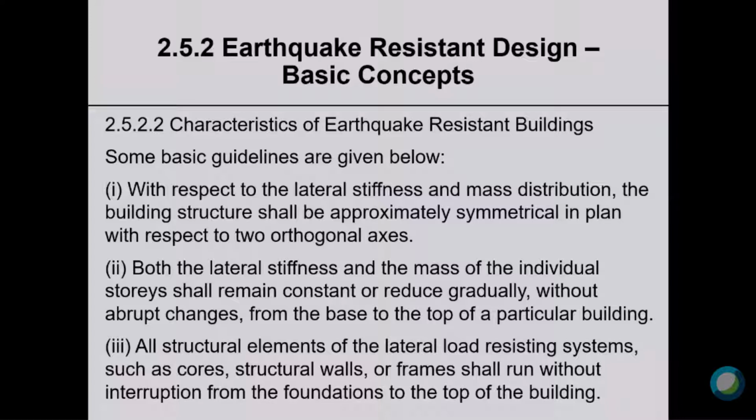All structural elements of the lateral load-resisting system, such as cores, structural walls, or frames, shall run without interruption from the foundation to the top of the building. That again doesn't happen. People want their bottom stories, the ground level story, wide open for ballrooms or stores or whatever, and then one level above you start with the walls and the partitions and different occupancy.